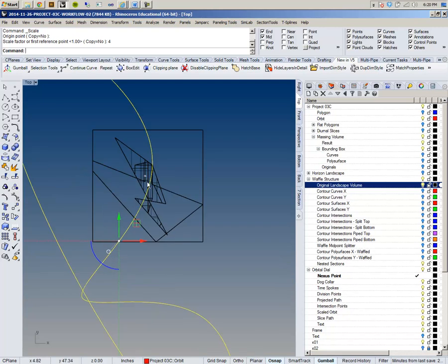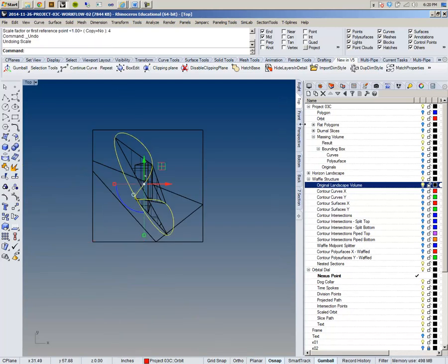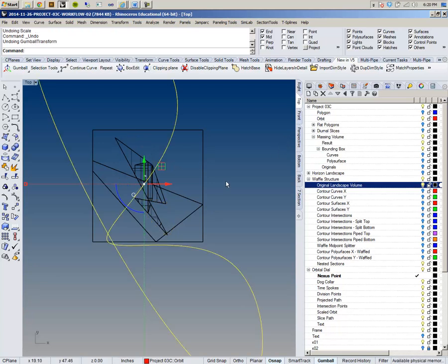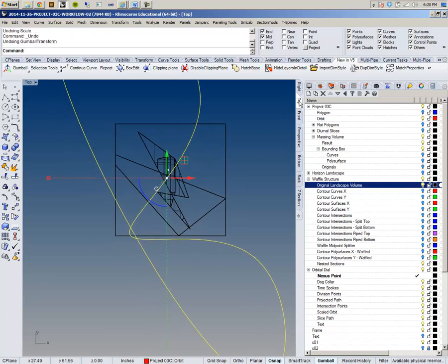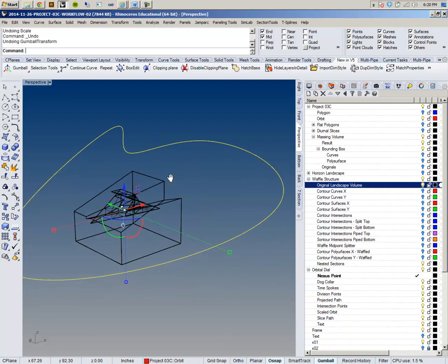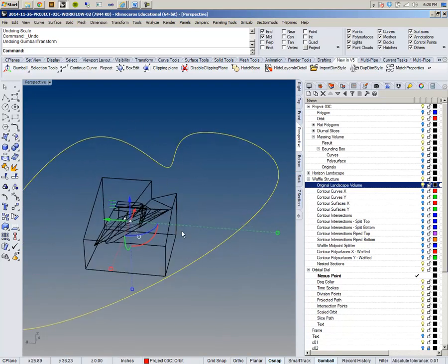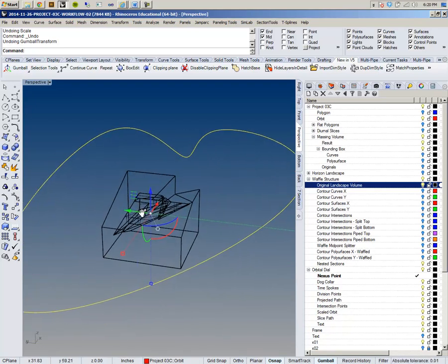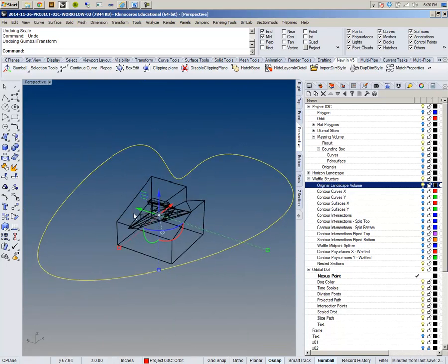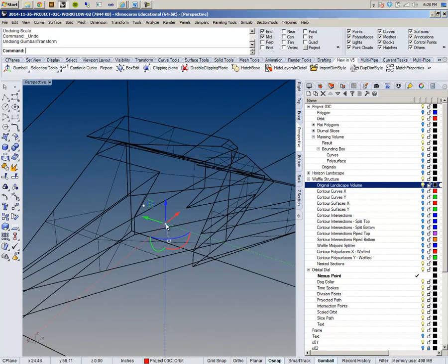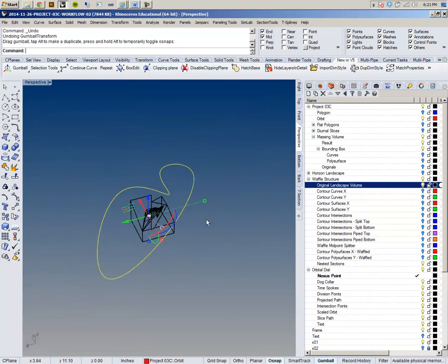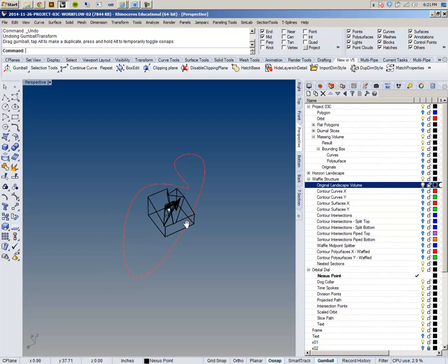Mine is a little bit off because I rescaled it with the gumball, which was not the right thing to do. So I threw off the axis of it. This is 2 uncorresponding points, so I'm going to move it back over to the way it used to be, like that, before I double dipped. So don't use a gumball, just use the scale and try out 4.